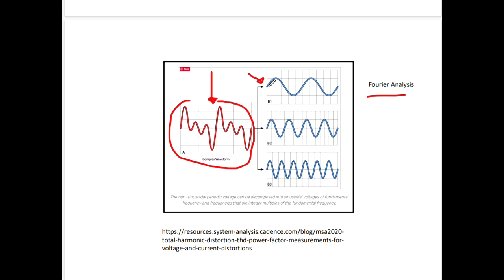It's got a frequency, an amplitude, and a phase. I don't want to get into phase. And then it's got this harmonic and that harmonic. And we analyze it to figure out the frequencies of the harmonics, the amplitudes of the harmonics. Forget phase. And now we know what built this signal, how it was built. This is exactly what we're doing when we analyze total harmonic distortion.